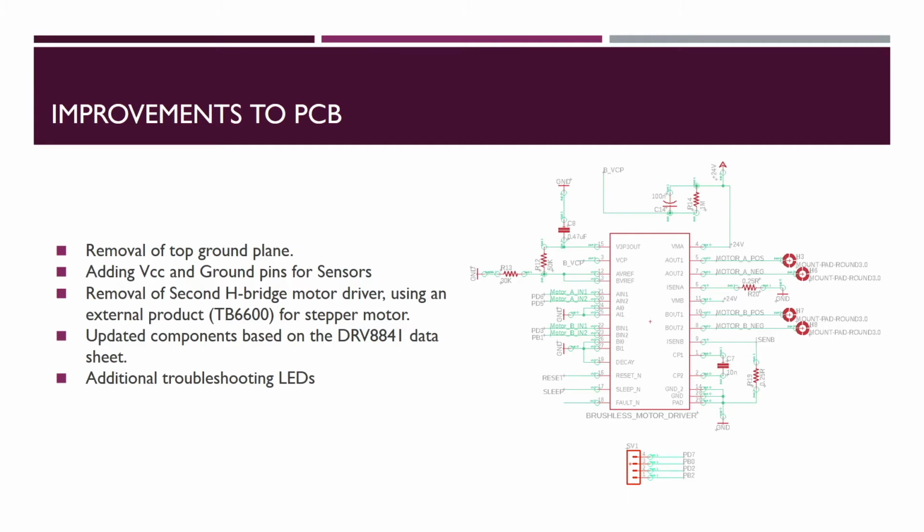We also had to add additional pins for the sensors. Each sensor needed a dedicated 5-volt VCC pin and a common ground pin with the rest of the components.